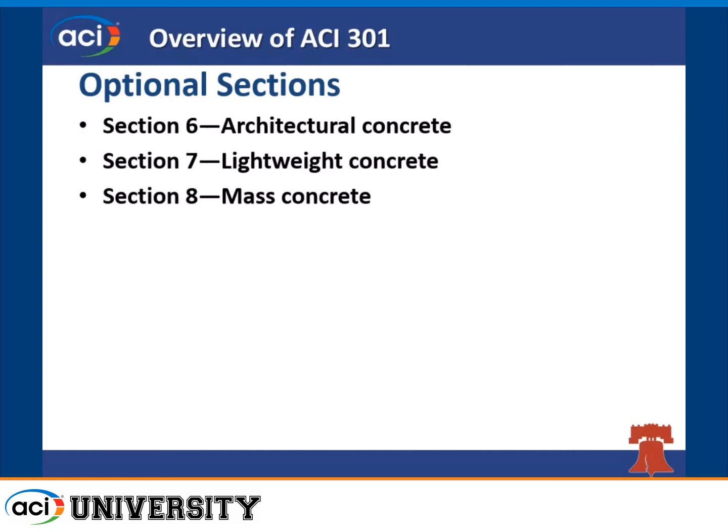It might be the best way for you on one project, but nowadays most people look at their thermal control plan a little closer and have successful concrete placed at 90 degrees, 100 degrees, and can still be mass concrete, but they need thermal control, they need cooling, they need protection. So that chapter has grown quite a bit over the past 10 years. We also greatly increased the post-tension concrete chapter to first, I would say, in 2010, write a lot of new provisions, but then in the 2016, what we did is we deferred to the Post-Tensioning Institute guys. And so they have mandatory documents available in our industry, and we now refer to those.